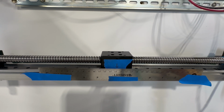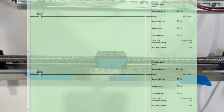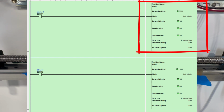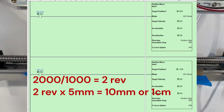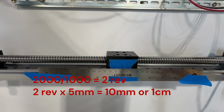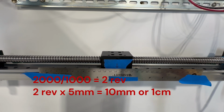Every time I hold the forward button, the slider will move 1 cm. Let's look at the PLC program for more detail. I programmed the PLC so that when I hold the forward button, it will control the driver to drive 2000 pulses. Remember that I set the driver to 1000 pulses per revolution. Which means the motor will rotate 2 revolutions when I hold the forward button, and the slider will move 5 mm each revolution. Total is 10 mm or 1 cm.